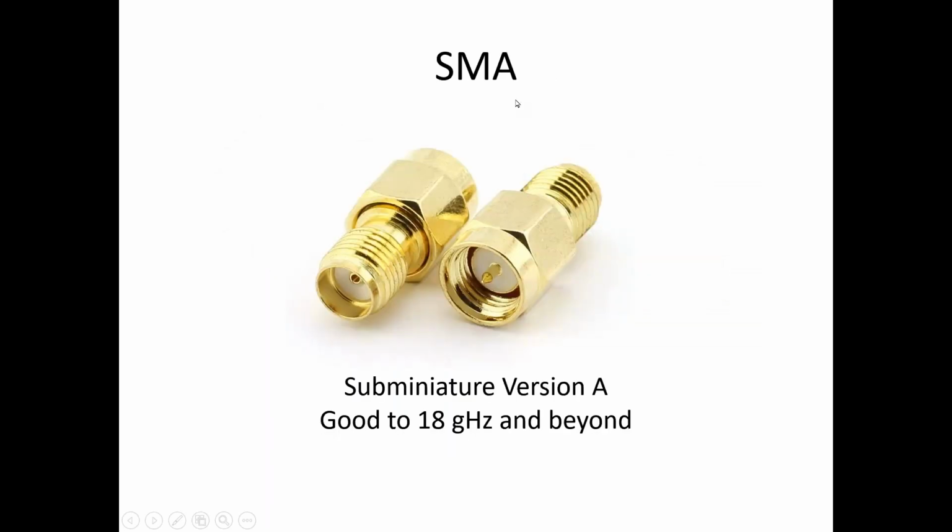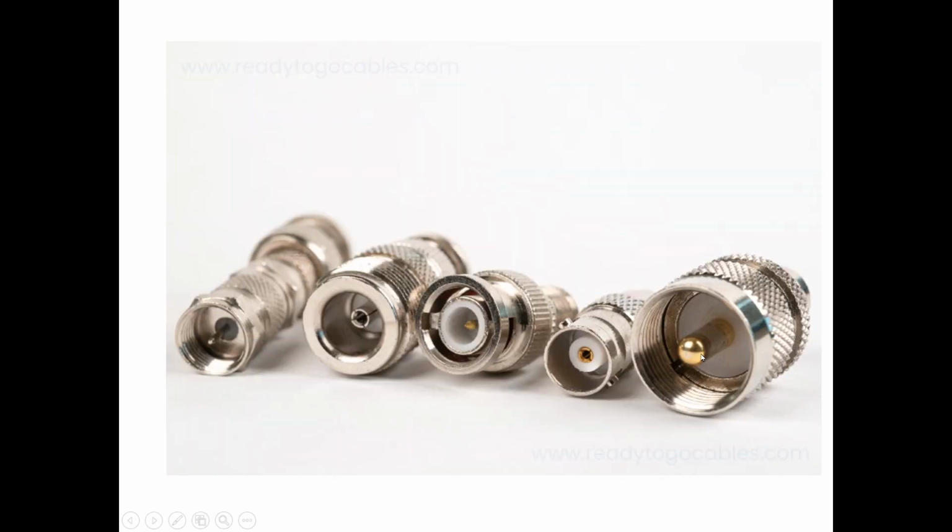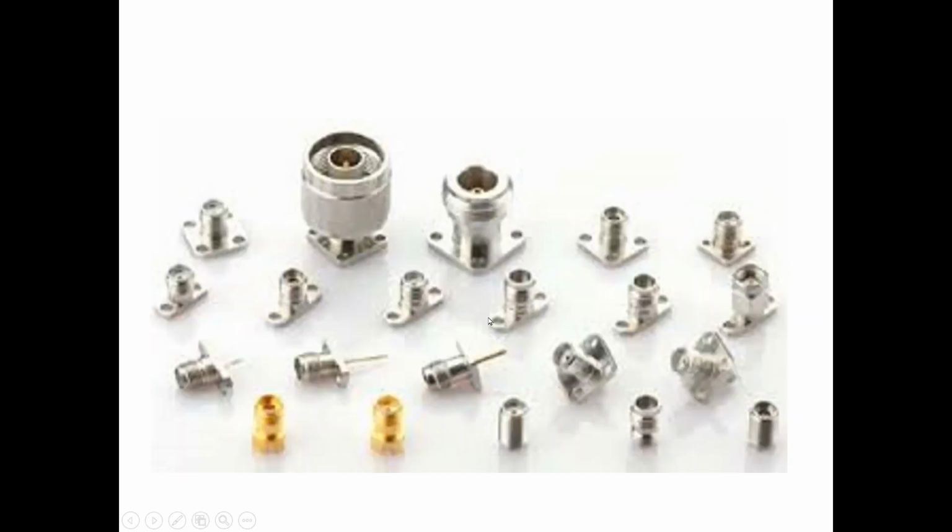A very popular connector right now is the SMA connector. This is on a lot of your HTs. Notice how high it can go in frequency, 18 gigahertz. The reason is that there's a lot of Teflon in here. You would not put a lot of voltage through here. It's a small connector, but it can certainly handle very high frequencies. SMA, sub-miniature A assembly.